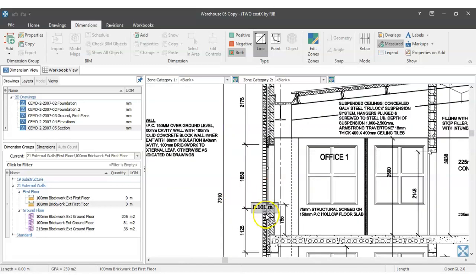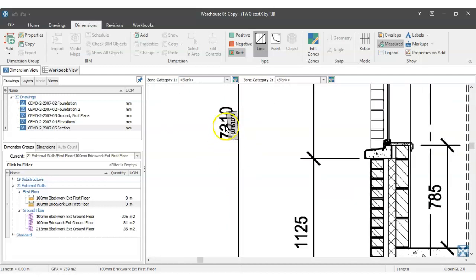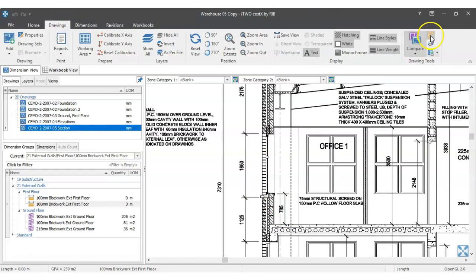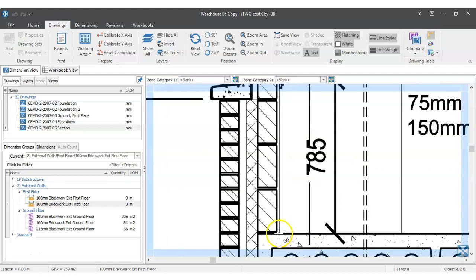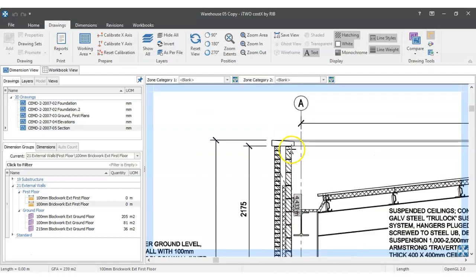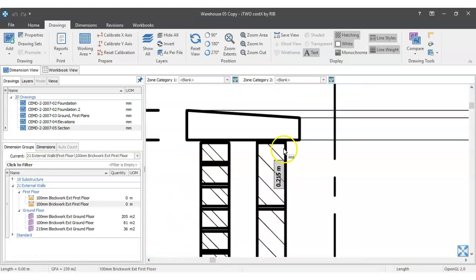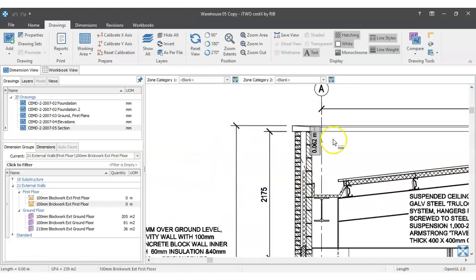No, there isn't. I could extrapolate it by basically taking 2.7 from 7.3. You can do that if you want, or just do a quick little measure distance. Start here at the first floor all the way up to the underside of that, right, including mortar. 4.5. It says 4.51 there, but I imagine it's 4.5. So let's go with the 4.51.